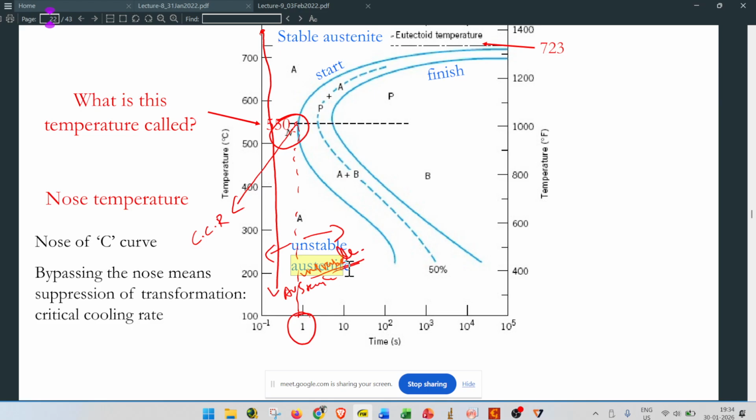I got it. Thank you. Yes, because carbon tries to keep the austenitic phase only. It does not like to form the martensitic phase immediately. If the carbon is increasing, it will try even more to retain the austenitic phase. The martensitic phase only forms when we are lowering the temperature. So if it is retaining the austenitic phase, we have to lower the temperature further to form the martensitic phase. That's why it lowers the martensitic temperature. Okay, sir, thank you.